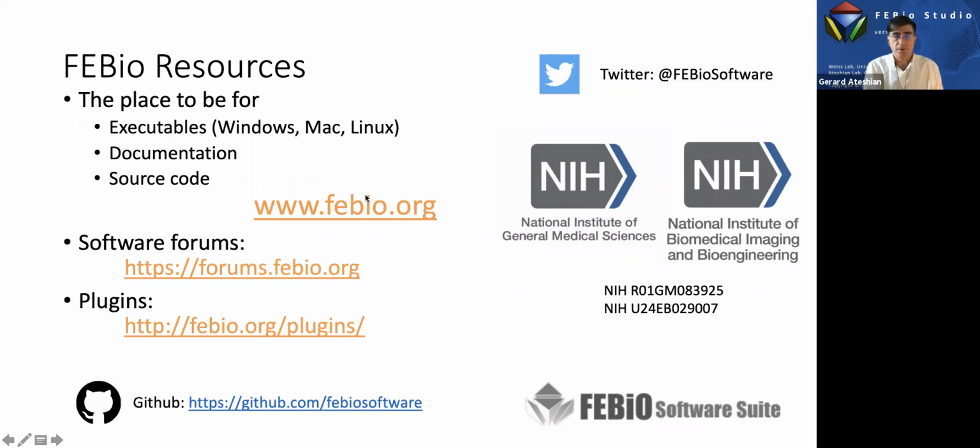And John Peloquin, you said, regarding the oscillations of fluid pressure in the uniformly spaced mesh, is it possible to correct this by other means, such as a different solver? So yes and no. People who've done porous media theories computationally have long suggested different ways. There are what we call stabilization methods, where you artificially introduce a parameter in your equations to minimize the oscillations.